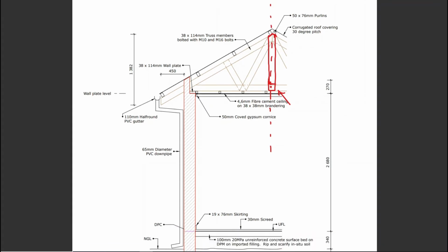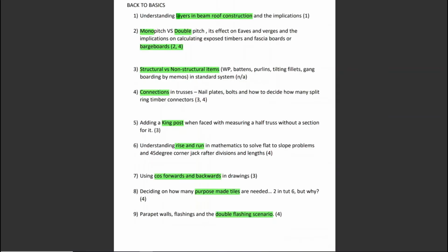But there are scenarios where this could come up and they will ask you, and you're going to have to use your own brain to figure out and design a king post and a half truss. And at this top section, because you got 1, 2, 3 coming through, you might have an M16 there. Maybe you want your king posts. I don't think they stop short. I think they typically go through. So you would use a bolt. That is the story with the king posts.